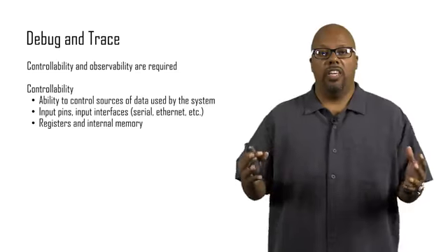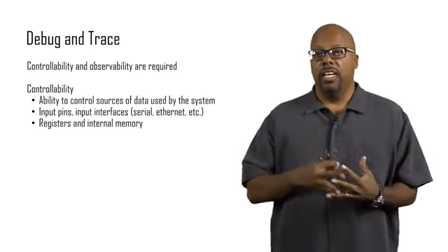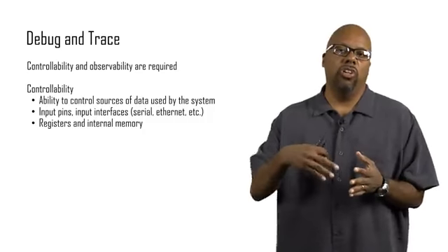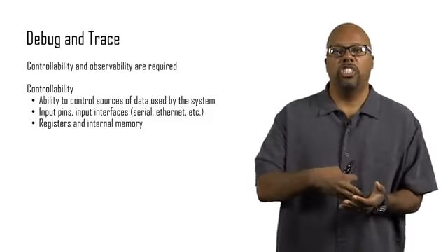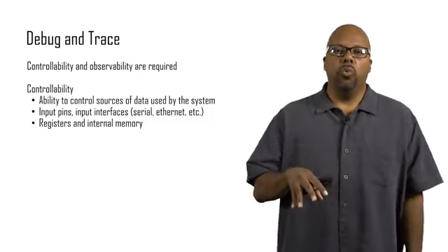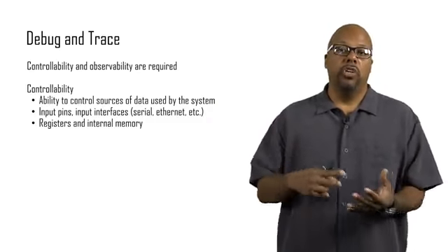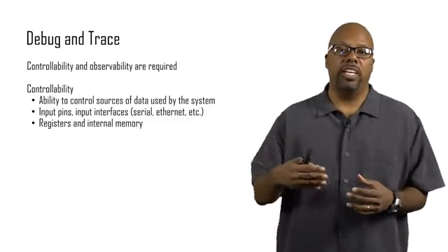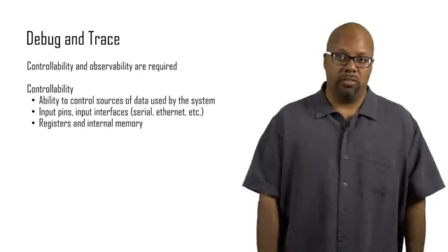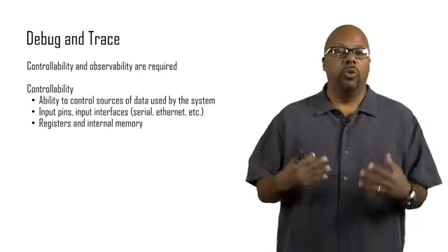Now, the input pins aren't the only thing that you would like to be able to control. In addition, you would optimally like to be able to control the internal data, meaning the storage elements, the registers, and the memory inside the chip. We won't be doing that in this class. I'm just saying optimally, if you're doing this professionally, you don't just say, let me control the pins. You go straight into the device and say, OK, I'm going to set this register value equal to 10 and see what happens. I'm going to write some data into this memory location and see what happens. You would like to be able to do that.